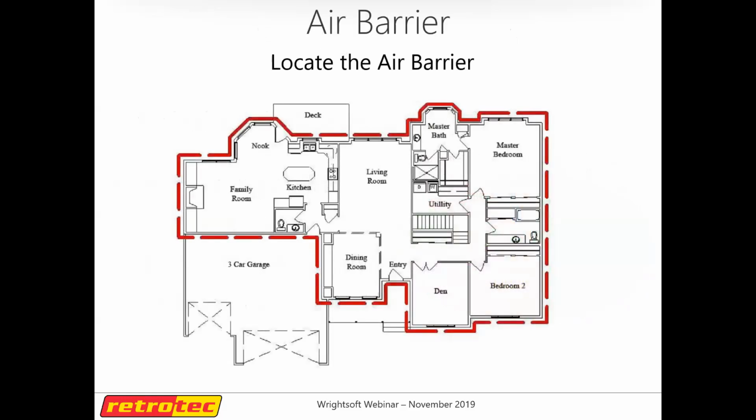Yeah, the house's duct system is something I try to teach a lot of the HVAC guys. If I have any HVAC professionals in the room, it's not a bad way to think of it. Your supply is connected to the return through the envelope. Another way of looking at a door between, say, the kitchen and the hallway, or the bedroom and the hallway, is just a big damper. Exactly. You close that door and there's not a return air pathway. You're going to positively pressurize the bedroom and create a negative pressure outside the building. It tends to draw air in and push air out, exacerbating infiltration issues, and you get bad airflow. It's like all kinds of badness.